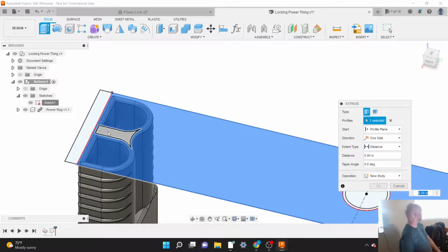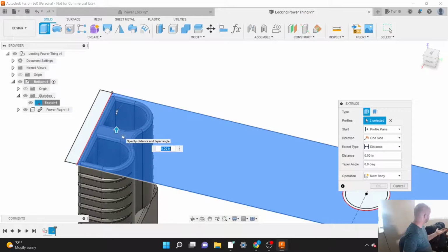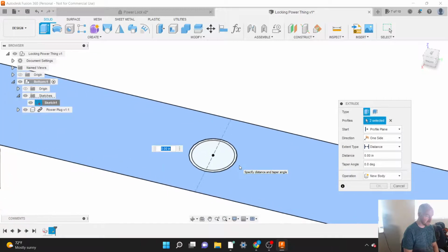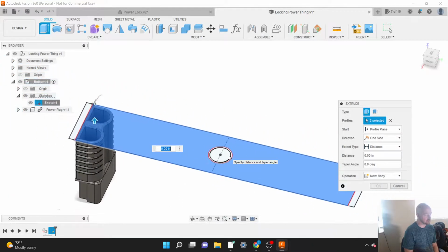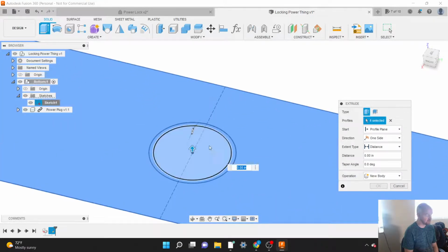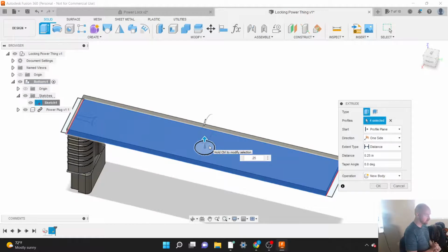And when you create your sketch on an existing surface, it carries over some geometry from the edges of that surface. It's kind of like invisible lines that are there, so you just gotta watch for that when you create a sketch on an existing surface. And I'm not going to highlight those bits of that circle. I changed my mind. I'm going to highlight the bits of the circle there. And I'm going to extrude this a distance of 1/4 of an inch.